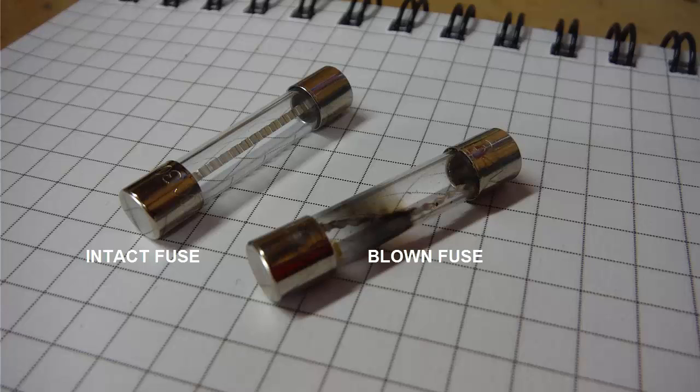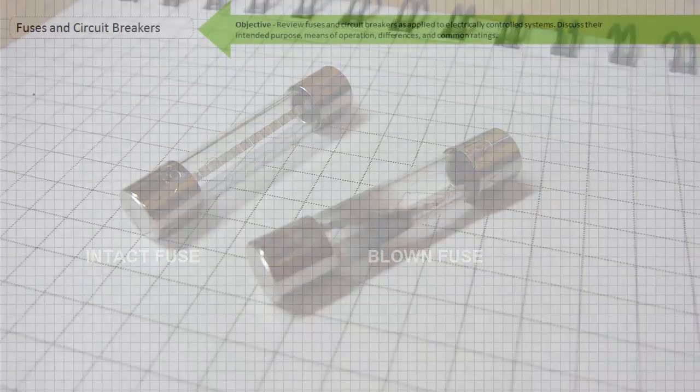Fuses differ from traditional switches, though, in that fuses are one-time use only. When a fuse blows, it is rendered inoperable, and here's the important part. Once the fault that caused the blown fuse has been identified and rectified, the damaged fuse must be replaced with a functional fuse with the correct rating.